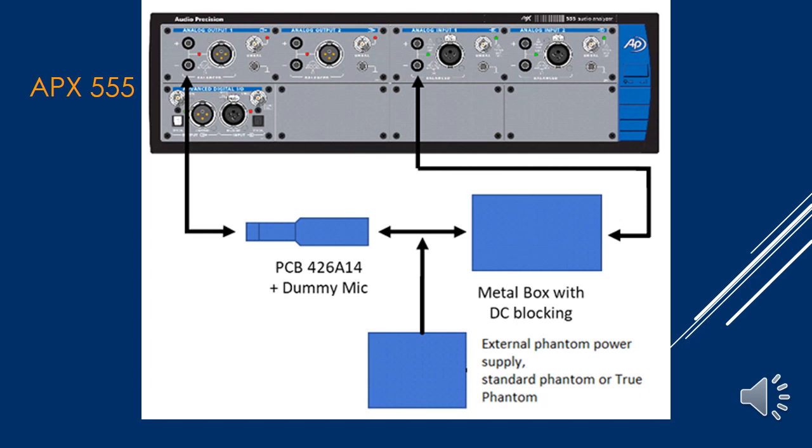So here's just a little bit more information on that. And that test box in here, that's basically to replicate this part of the circuit. In fact, the first set of measurements that were done, this was not done there, and then we realized we need to have that equivalent loading on the 48-volt mic preamp to properly characterize the performance.